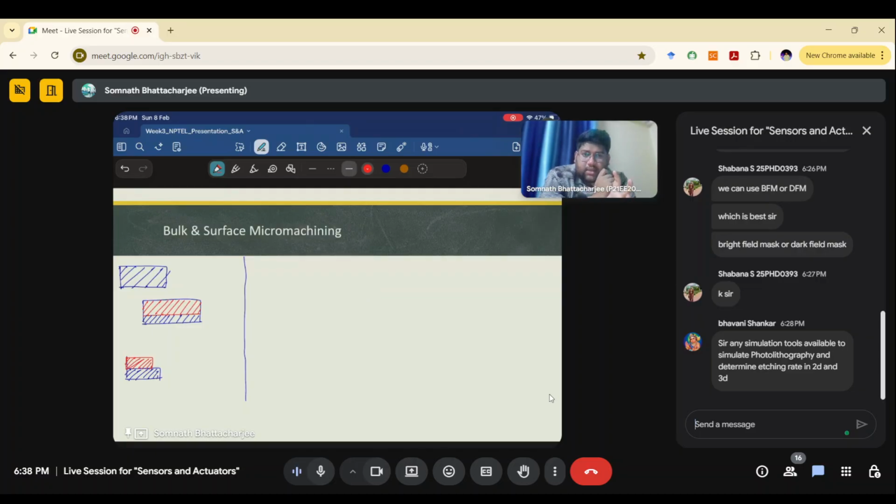Think of the basic understanding of ALD before. ALD creates atom by atom layers, and we are depositing a very ultra thin and very uniform layer. So why do we need photolithography in this case? If we need to pattern a very highly uniform and ultra thin layer as well.